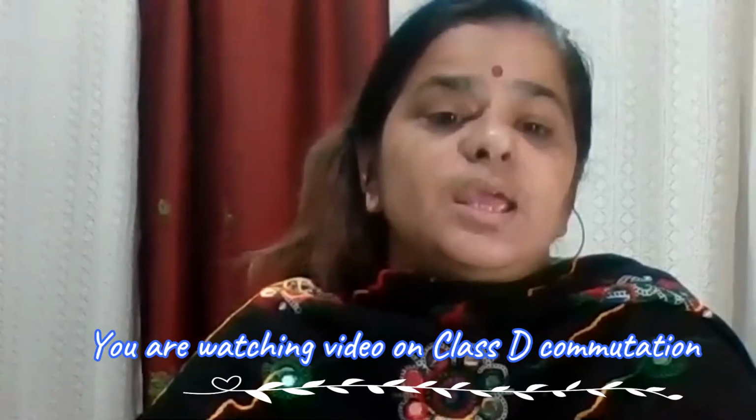The second is current commutation. In case of current commutation, with the help of some external circuit, we try to flow current through the SCR in the opposite direction, and at the time when the current flowing through the SCR becomes zero, the device will be off. That kind of commutation is called current commutation. In this video, I am going to discuss class D commutation. That commutation is a type of voltage commutation.